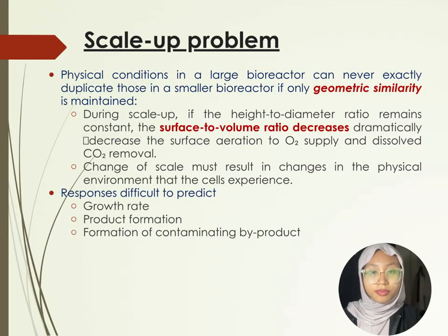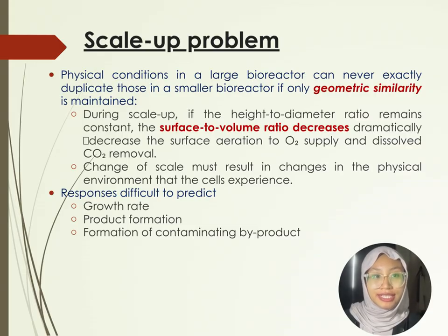Thank you. In these sections, I will explain the scale-up problem in bioreactors. When a fermentation process is transferred from a small laboratory bioreactor to a larger industrial bioreactor, it is impossible to maintain exactly the same physical conditions while only preserving geometric similarity, which means keeping the same height to diameter ratio.